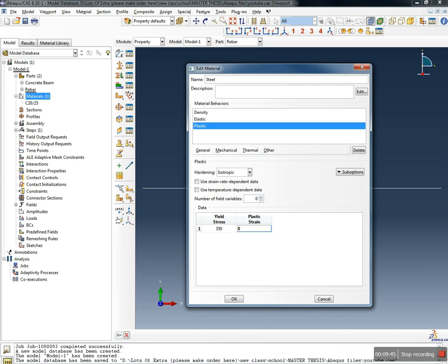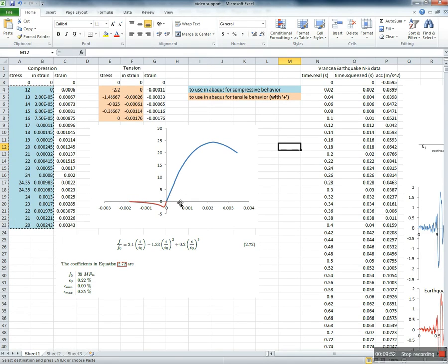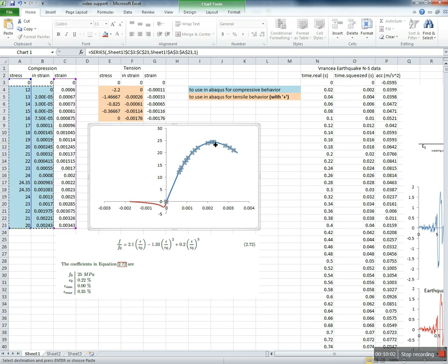Okay. Maybe to make another mention about elastic strains and plastic strains. Plastic strains are the same as inelastic strains. If you are at one point, let's say this point right here, and you want to know the inelastic strain at this point, you have the total strain, which is right here, about 2.2 per mille, and you subtract the value obtained by unloading along the Young's modulus, like this. So you will have this part, the elastic part of the strain, and what will remain when you subtract that from the total strain will be this part, which is the plastic part of the strain.